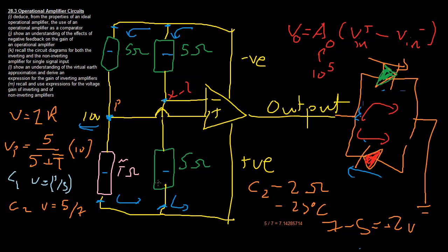For example, in an oven, we don't always want to cook everything at 180 degrees. Sometimes we want to cook things at 220 degrees. So this one will often be a variable resistor, so that we can determine what the threshold has to be for this resistor here in order for it to overcome the limit. So we can change the limit. We can make the limit that you have to have more than 2 volts. We could have it that you have to have more than 4 volts.